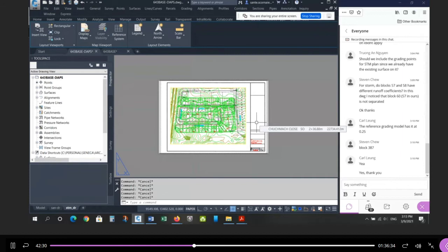So the last thing to design after this submission is the pipes, sanitary and the storm pipes, right? Doing your design sheet, getting all your sizes and slopes, drawing it in profile like I taught you last semester in CDA. Okay, any questions about the drainage areas?